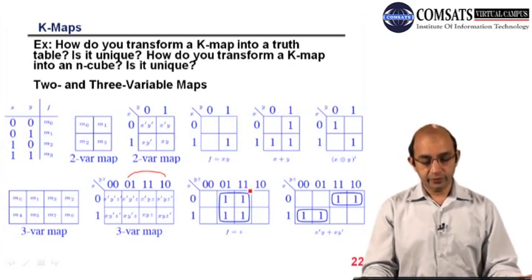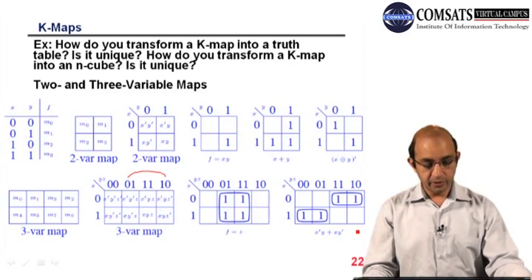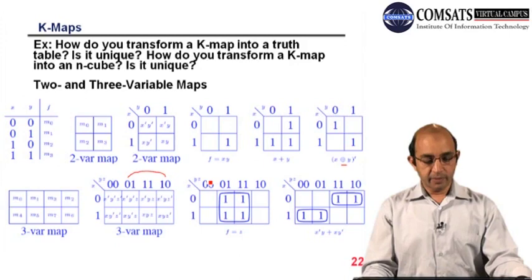And then what we need to do after the mapping from the truth table to the K-map is look for the groups. First, we look for the maximum number of ones that can be grouped. Here we can have only a square. Then we look for the pairs. So these are the corners, and the corners can be replaced by this XOR functionality. So here we can see we have the K-map simplification.